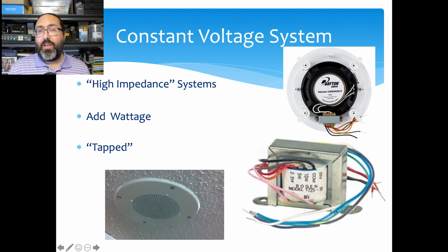If you've taken lighting class before and you've ever done ME paperwork and you try to figure out if I can put this many lights on a circuit, all you're doing is adding up the wattage and making sure that's underneath what that circuit can take. So, for instance, if you have four Source Fours and they're 575 watts and you have a normal circuit breaker at 2400, you can use four Source Fours. If those four Source Fours are at 750, then that exceeds that 2400 and it would pop the breaker.